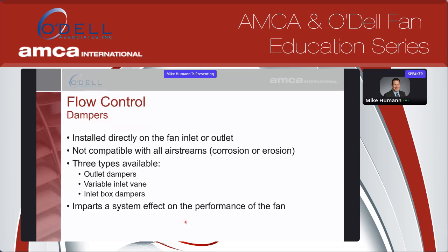Specifically, a large one is dampers. Those are directly mounted on the inlet or the outlet. And these are not compatible with all airstreams. Something to be cautious of is if there's corrosion or erosion, that's certainly something that can cause issues with dampers. You can get special damper construction, but it's just something to note and be concerned of. The three types of dampers that are available for a fan are an outlet damper, a variable inlet vane damper, and an inlet box damper. These dampers all impart a system effect to change the performance of the fan.